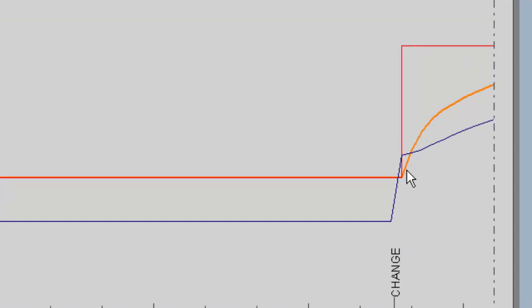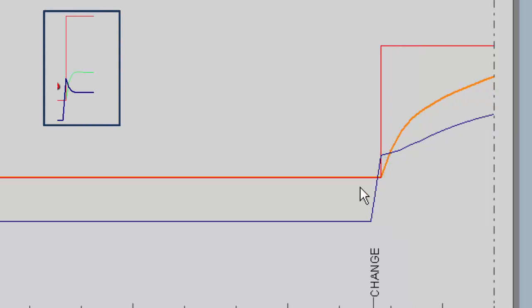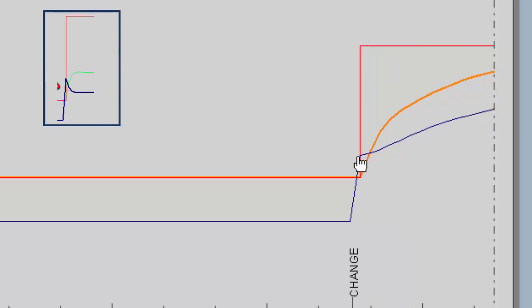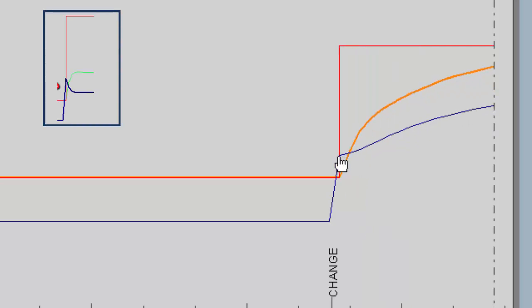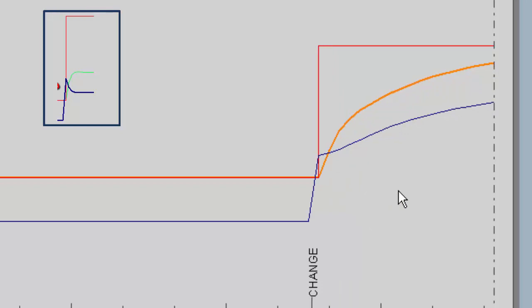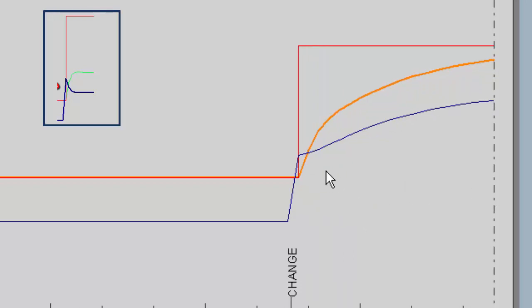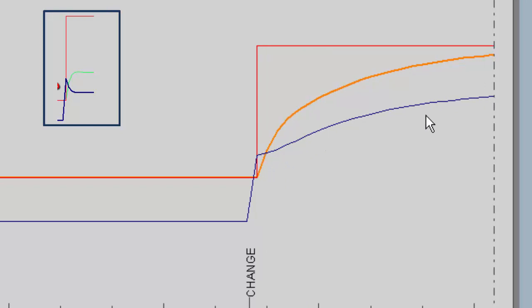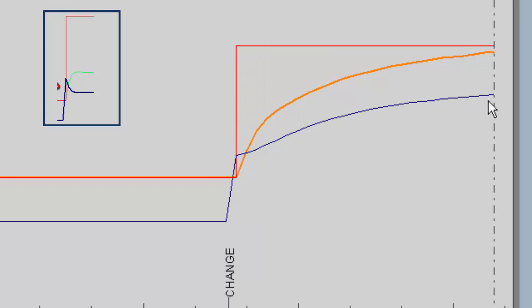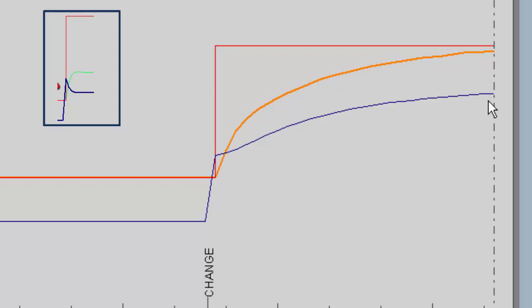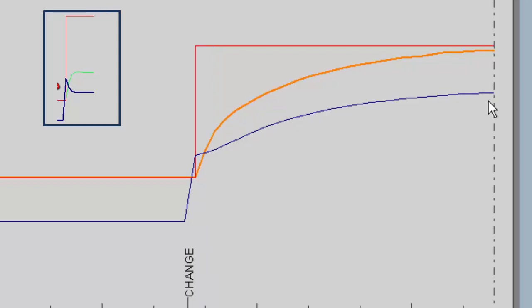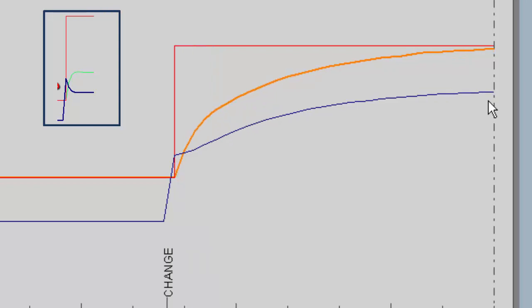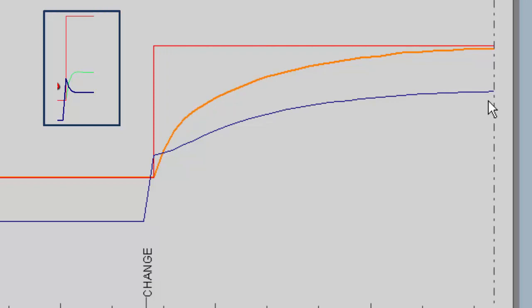Now previously, when there was no reset time, if you recall, and I'll show you alongside, the proportional action took effect where it came up initially like that, and then it came back down because there was no integral time or reset time. Slightly different now, you have the initial kick and then the reset time kicks in to bring you to set point. And that gives you the full effect of the PID algorithm.